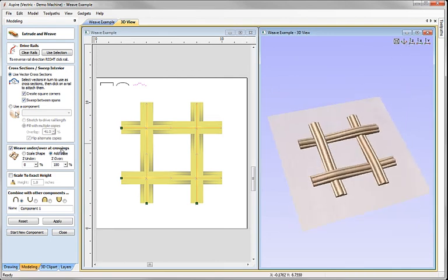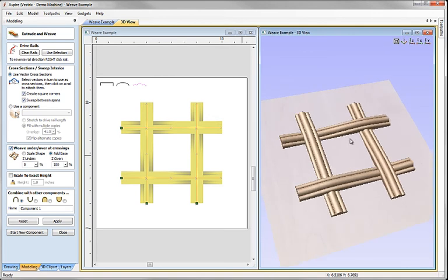Generally speaking, when we use the add base option, that is going to give us a finished model that will have a higher Z height than using the scale shape option. But for some applications, that's just the right one to use in order to maintain this consistency. If you're not sure, you can easily switch between these and they will remember the values that you associated with each one because they tend to be quite different. Typically for add base you may go between 0 and 100, 0 and 50, something like that. And for scale shape you may just slightly modify it to come a little below 100 or a little above 100 depending on the effect you're looking for.